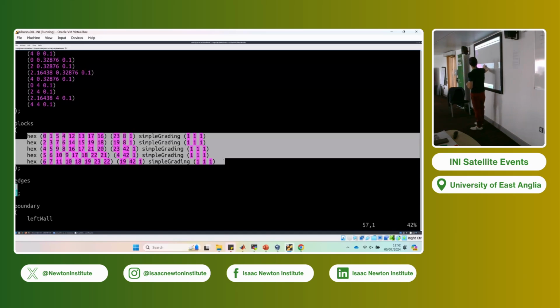If I was having 3 on the last number, along Z, your mesh would become increasingly finer 3 times every time, with a factor of 3 cell after cell. So 1, 1, 1 means that along the 3 coordinate directions, the mesh is uniform. In OpenFOAM, every time you see a parenthesis with 3 numbers, typically it is a vector with the 3 components.